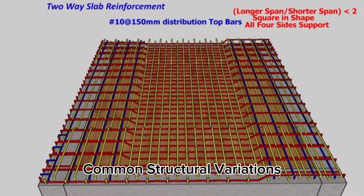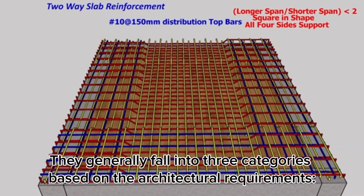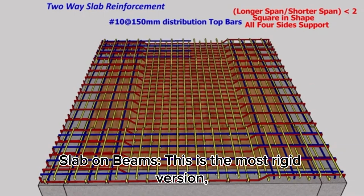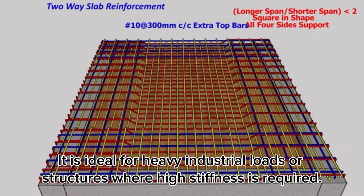Common structural variations. Two-way slabs are not a one-size-fits-all solution. They generally fall into 3 categories based on the architectural requirements. Slab on beams. This is the most rigid version, where the slab rests on beams on all 4 sides. It is ideal for heavy industrial loads or structures where high stiffness is required.